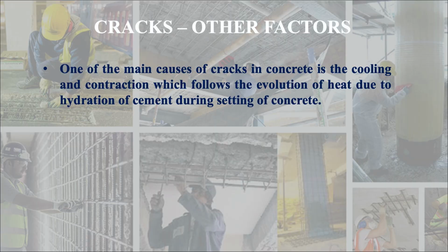Now, other factors include cracks. One of the chief causes of cracks in concrete is the cooling and contraction, which follows the evolution of heat due to hydration of cement during setting of concrete. You know that hydration is an exothermic process, so heat evolves on hydration of cement.